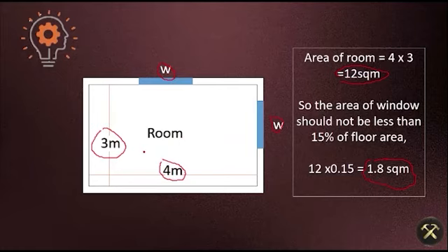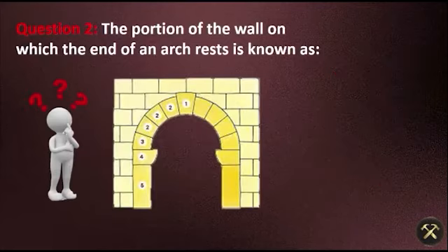So whenever you are going to construct or design rooms, your window area should not be less than 15% of the floor area. I hope you got this. It's clear now. Let's move to question number 2.